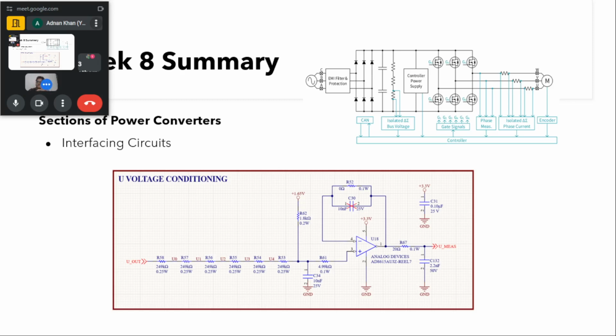So we want to condition these voltages and change their levels. For that we'll have this op-amp circuitry, which will change the level. By this we can also give offsets and so on, so we can then give this voltage that we have sensed to the microcontroller and take appropriate control actions in the microcontroller and provide the subsequent pulses to our devices.